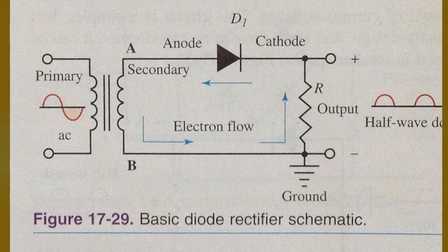The output voltage of the transformer's secondary also appears as a sine wave. The magnitude of the wave depends on the turns ratio of the transformer. The output is 180 degrees out of phase with the primary.